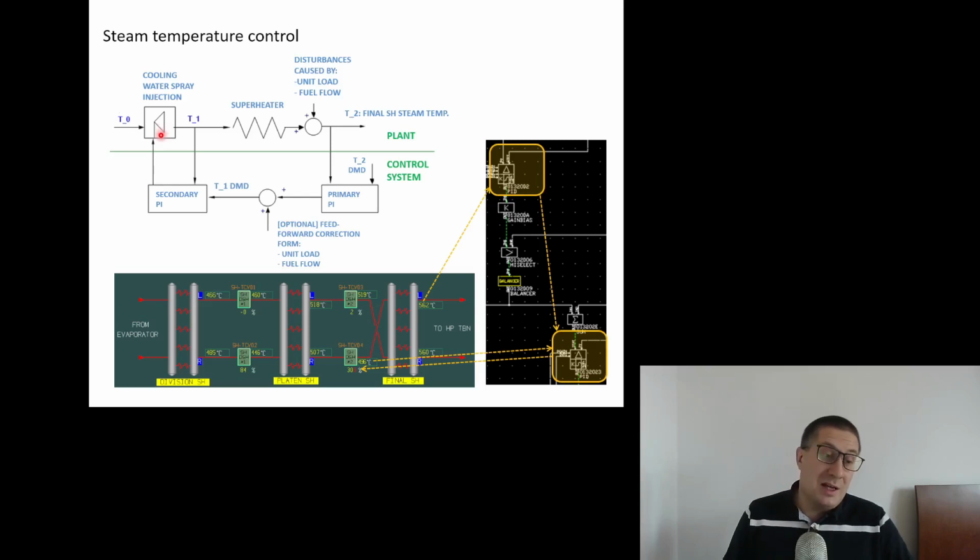Moreover, you know, I haven't mentioned this, but the characteristic of this cooling water injection is non-linear, right? So if the controller assumes that the reality is linear, and it's not linear, we will see that we add too much or not enough cooling water after a minute.